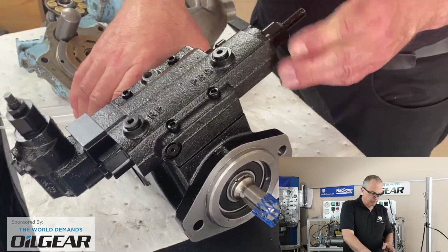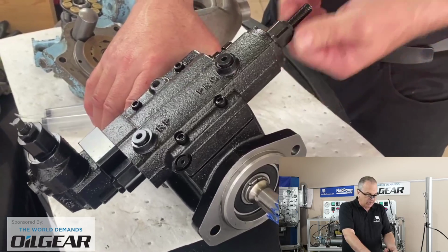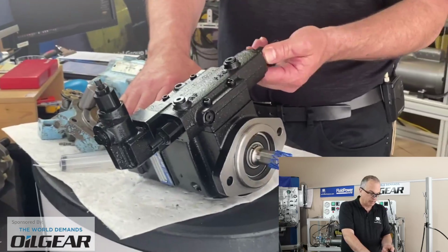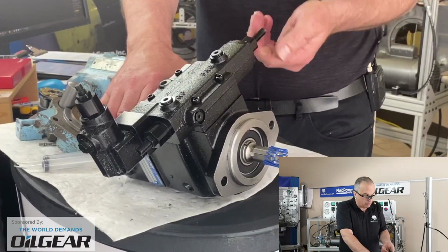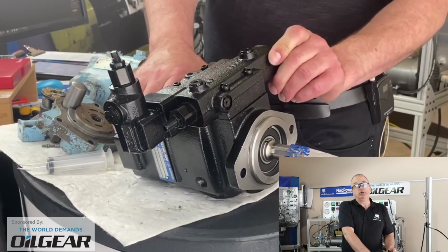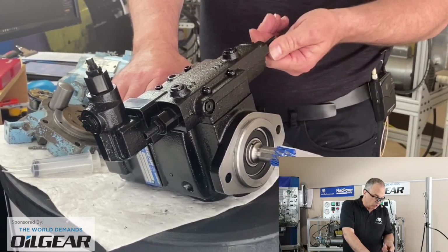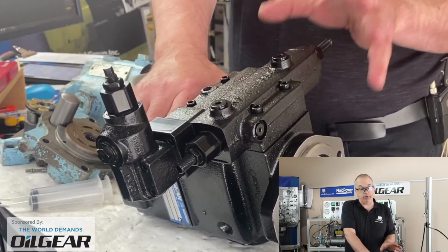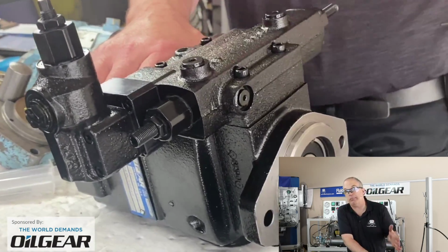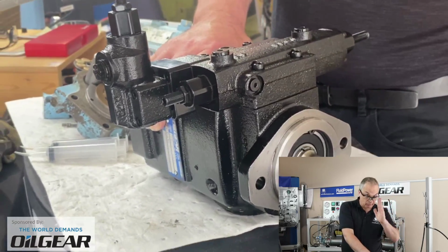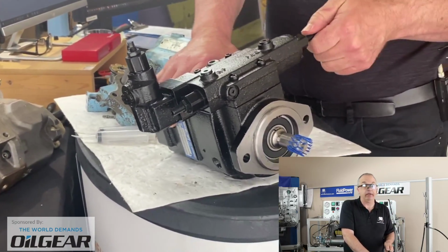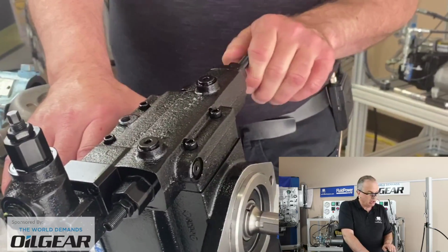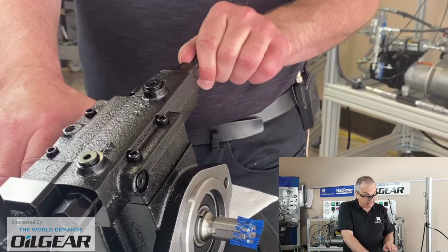And perhaps this one's not quite as common. You might be saying, hey, what's that one sticking out? Well, we deliberately ordered it with this. This is a minimum volume stop, or Q minimum. What happens if you start to turn that one clockwise? With Q minimum, if you dial it away from its factory setting, clockwise, you're going to set up this pump in such a way that the swash plate, when you go into pressure compensate function, will not quite make it to the 0 degree angle, meaning it's going to remain on stroke even once pressure compensate hits. Usually very small amount, if any of that is dialed in.